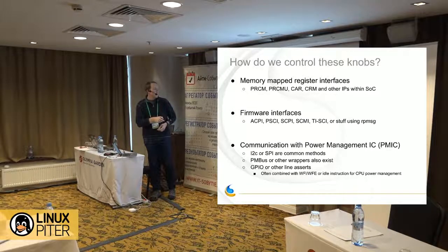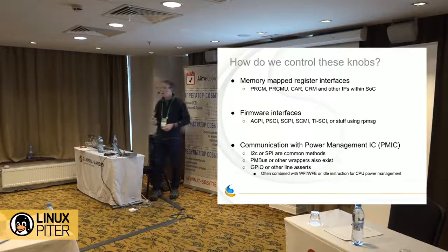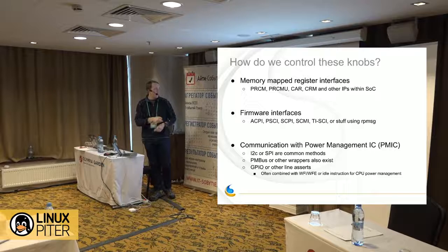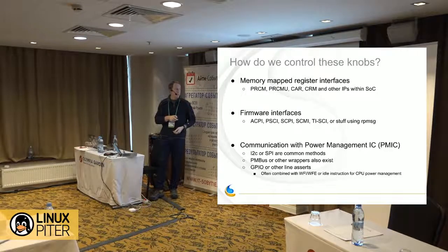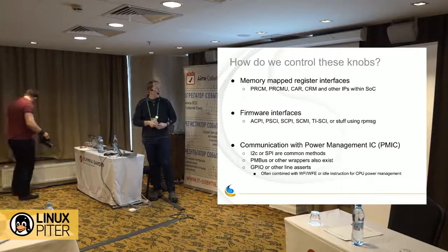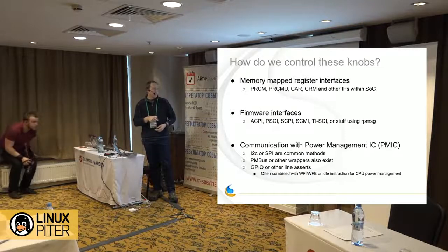There are also firmware interfaces. For a long time you mostly saw this in the Intel world with ACPI, where all the power resources you have to go through ACPI. We're seeing a lot more adoption of that in the embedded ecosystem now as well. ARM released PSCI, which originally only targeted CPU power management, but then SCPI did CPU performance management, and now SCMI is supposed to do the whole platform, all the different peripheral devices, GPUs and all of that. Texas Instruments released some patches for the SCI. I don't even remember what that stands for, System Control Interface or something. So firmware interfaces are starting, I think, to take over the world a little bit.